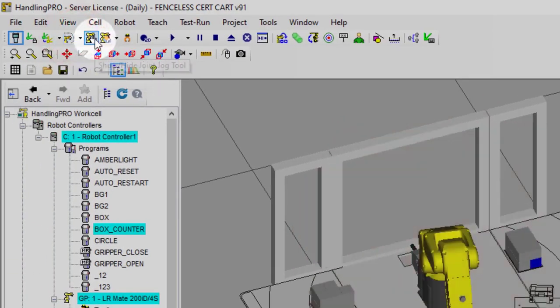We can also scroll over. Here you're seeing some other things like cycle starts. Like if we were on the robot controller, we can hit pause or abort. That's kind of like our emergency stop. Fault reset. These are all things that are on the teach pendant, but they're also built into the RoboGuide tool panels as well.